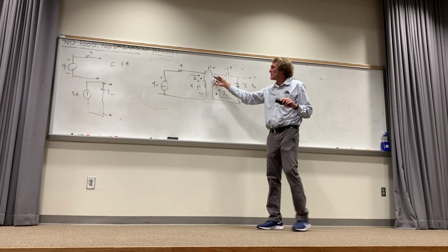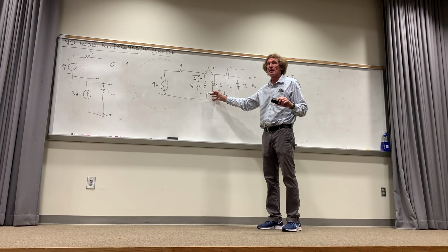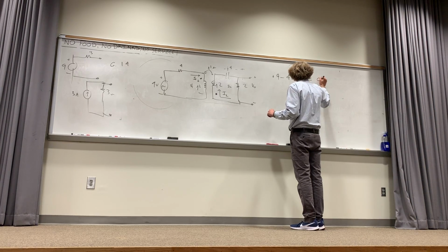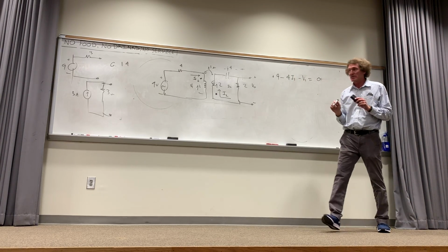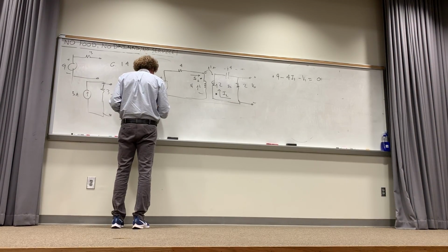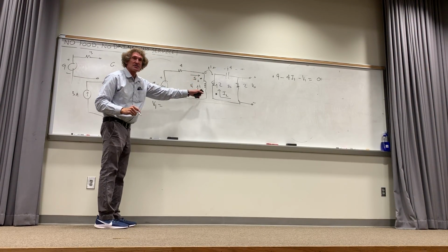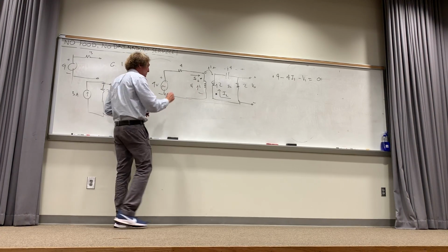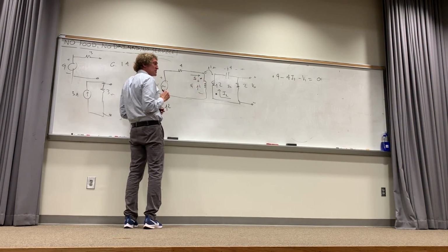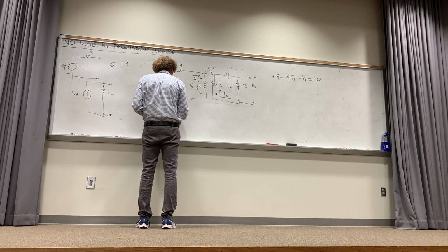And then it's going to be minus V1, right? Correct? You see that's V1 there? So it's minus V1 equals 0. I'm going to put in what V1 is in a second, but I want to break it out by its lonesome. What is V1? Well, V1 is the voltage across there, right? Which is going to be J omega, or really J2, that's the impedance of the primary coil times I1, right?